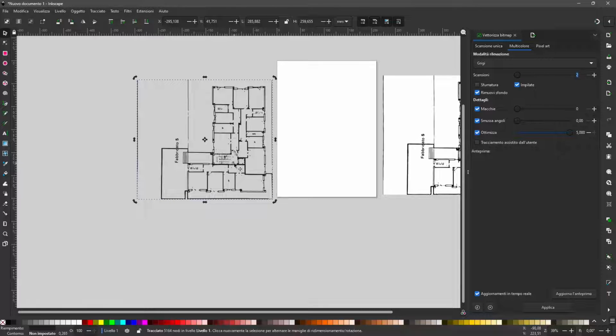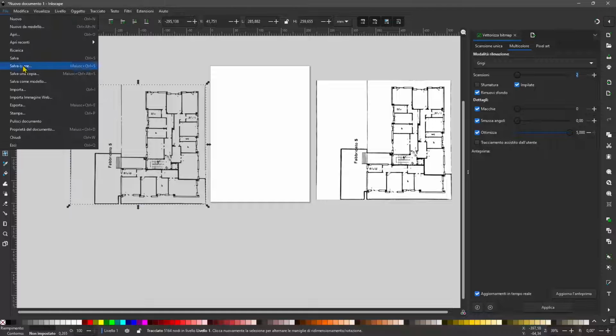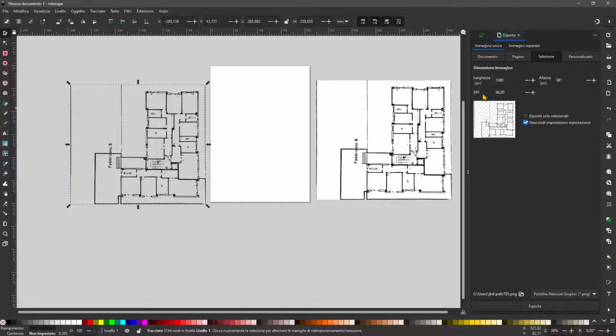And also you need perhaps to clean the image a little bit more from the text and the numbers and everything that you don't need. But once you're ready, you can take this and just export it. So to export it, you go back to File, Export, and here you can choose the selection only. So choose selection and choose as graphics. You can use scalable vector graphic or SVG. This is going to export it, and use plain SVG actually.